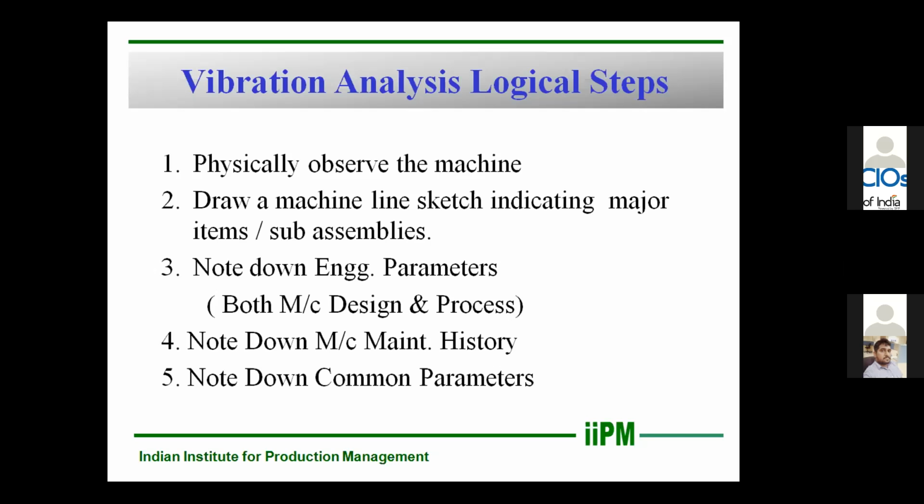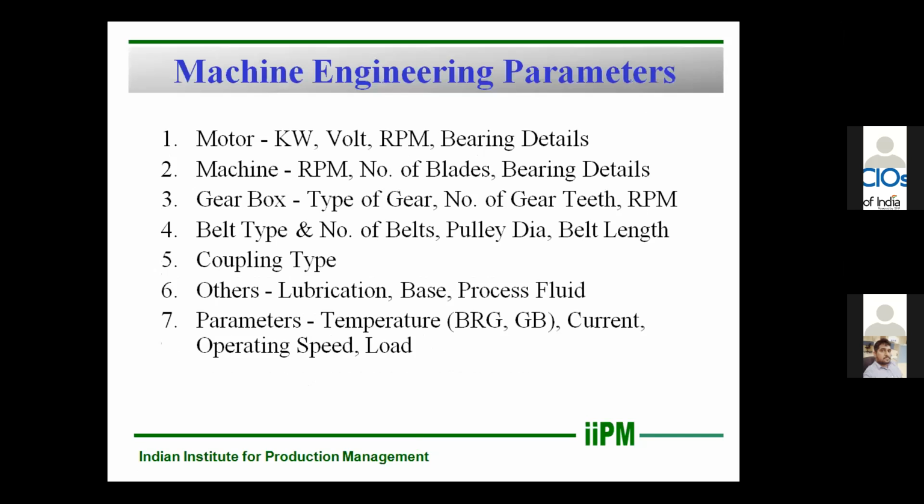When a detective finds a thief, he needs to ask what happened in the past, which places you have gone to, what all maintenance activities. Vibration is just like that: you are a detective, and you are going to find out the faults in a machine. So note down the common parameters I mentioned, like temperature, oil condition, whether there is some leakage, and whether some hot air is passing. You need to see that.